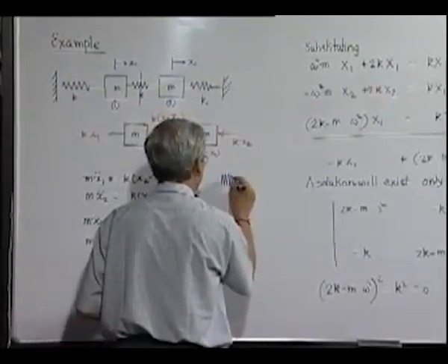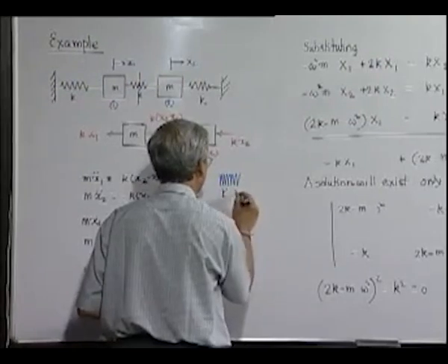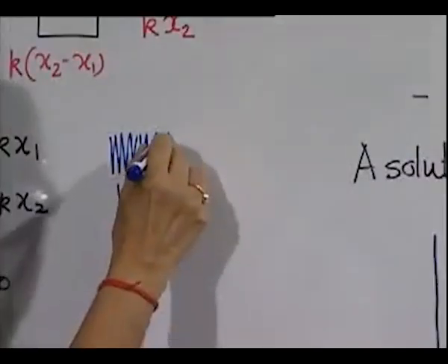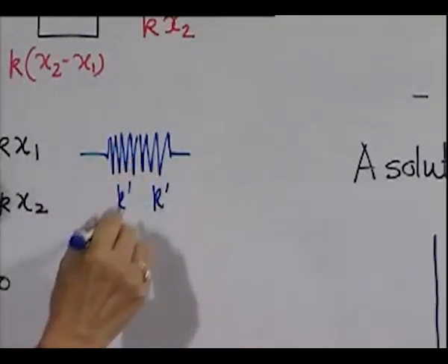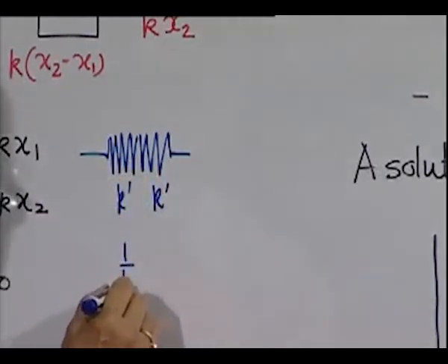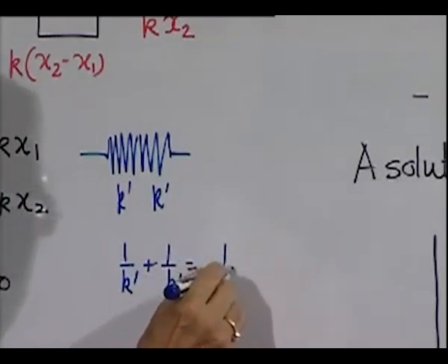So it becomes again two systems with this mass, one spring of stiffness k, and this half of the spring, whose stiffness is obviously double, because if we make the length of a spring half, then its stiffness is twice, because two halves of spring,